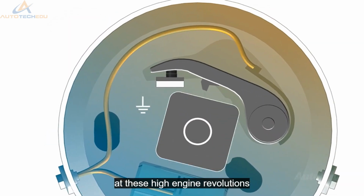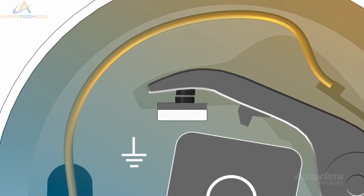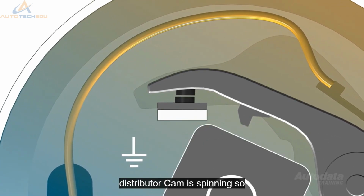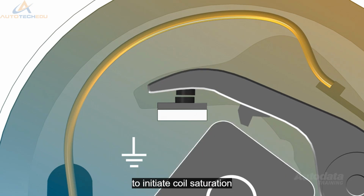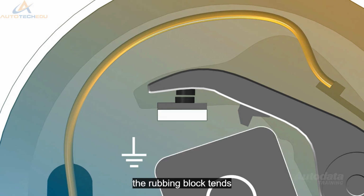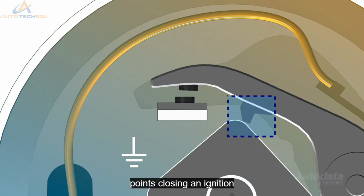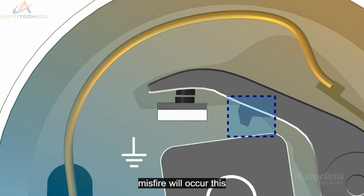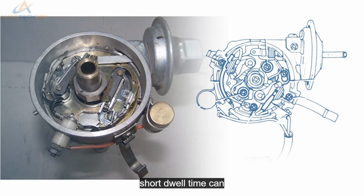At these high engine revolutions, the mechanical contact set may suffer from point bounce. This is because the distributor cam is spinning so fast there is no time for the points to close to initiate coil saturation. The rubbing block tends to float between the two high points. Without the points closing, an ignition misfire will occur. This short dwell time can be improved with the use of a twin contact breaker system.